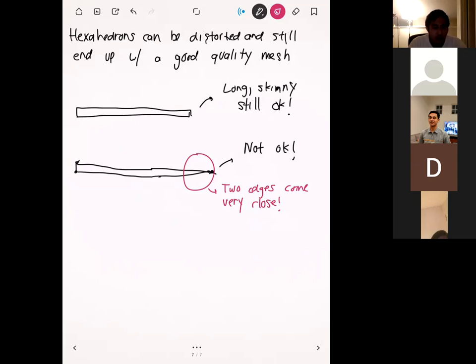To get into the reason why would take a long explanation, but basically, because of the way the shape functions of the tetrahedron are, if you have an area of your element like this, it really deteriorates the accuracy of your results.